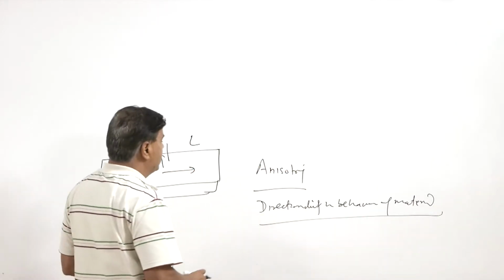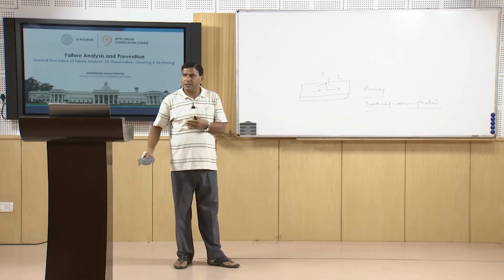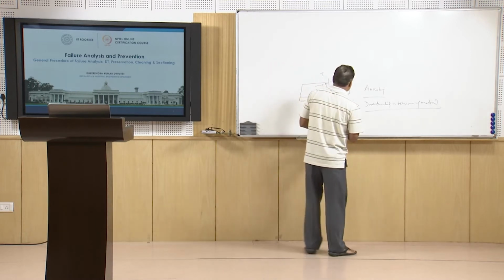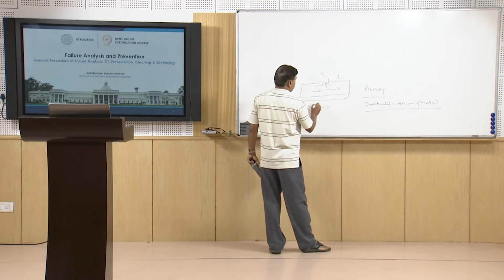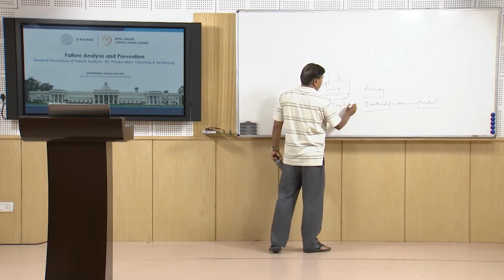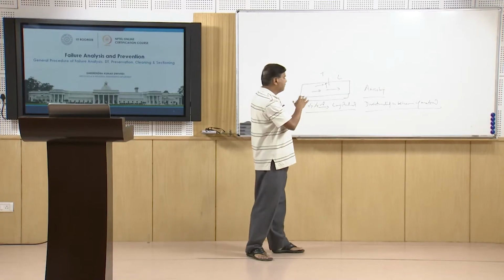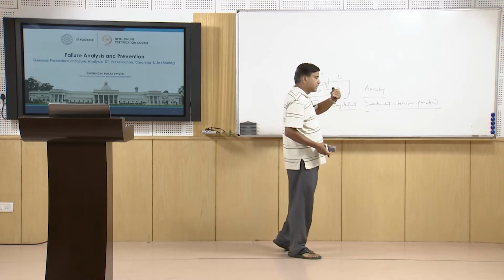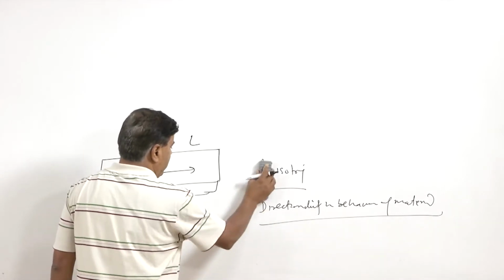And this must be investigated if the component is experiencing the stresses in the transverse direction, which may be more crucial as compared to the stresses which are acting in the longitudinal direction. Since the material offers much better yield strength, ultimate strength and percentage elongation in the longitudinal direction as compared to the transverse direction, it is important also to consider the behavior of the material in the transverse direction. We have also observed that not just the tensile properties, but the toughness of the material in the transverse direction is found to be lower as compared to that of the longitudinal direction.